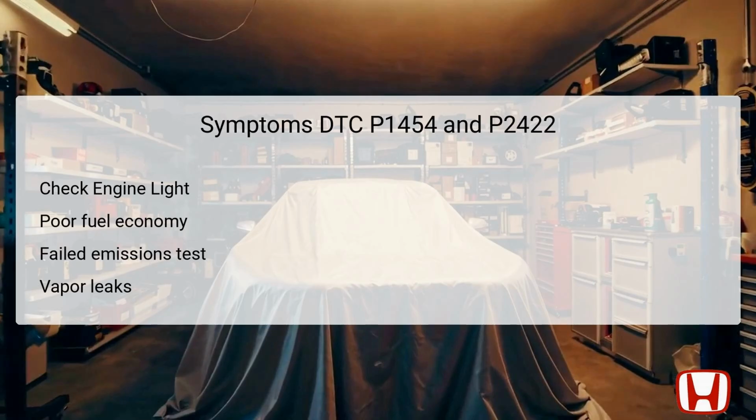fuel vapor management. Additionally, when dealing with DTC P2422, issues such as the vehicle failing an emissions test may occur as the ventilating mechanism for the fuel vapors is compromised. Lastly, there may be signs of fuel vapor leaks, which not only points to regulatory non-compliance, but can also lead to dangerous fumes being released into the environment.